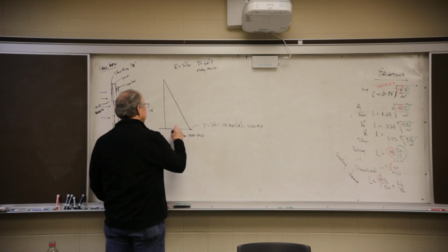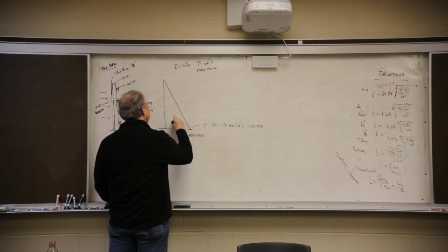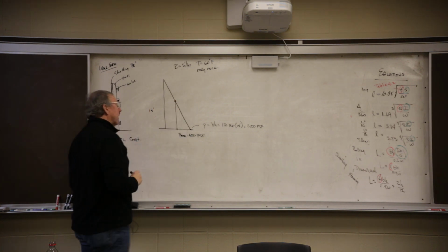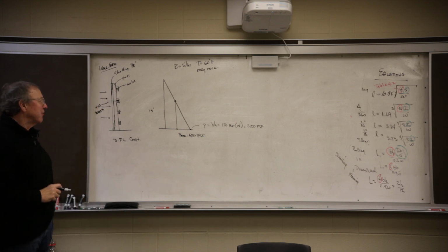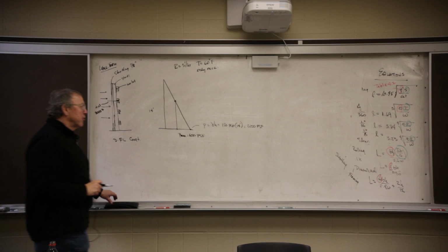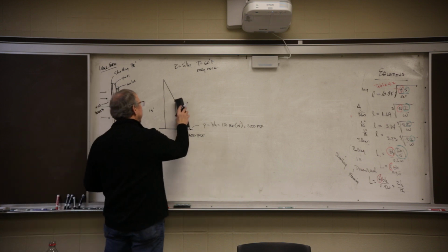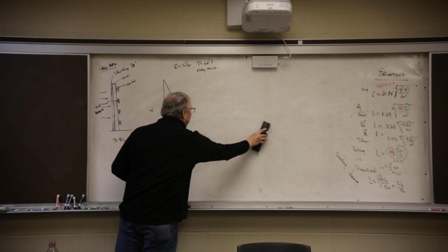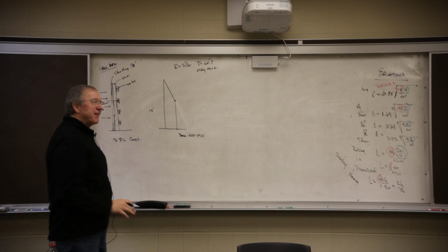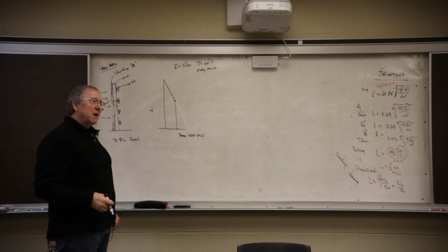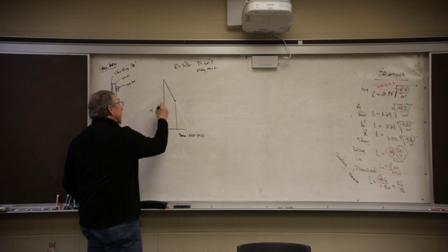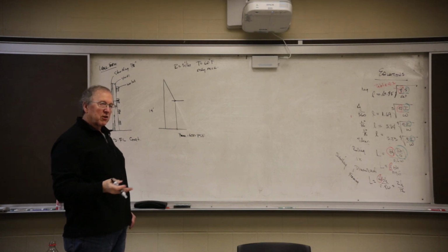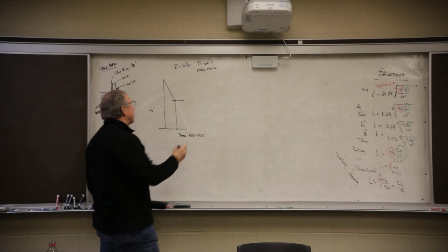So now, plot it. Draw a line straight up. That line is going to intersect the straight line curve gamma H. So my pressure distribution is going to look like this now. I can erase this. This doesn't have anything to do with me anymore. There's the pressure. And how far down is the pressure going to become 600? Well, how many feet of concrete do you have to stack up, if it weighs 150 pounds per cubic foot, to weigh 600 pounds? So all we've got to do is